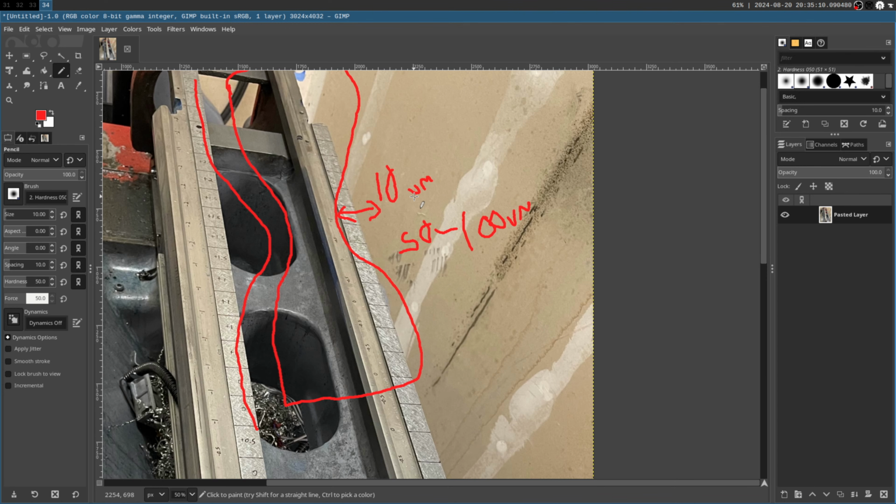The Monarch 10EE that I have, I think its ways were down to 2/10, which is 2/10,000ths of an inch, which is like 5 micron. I think from the factory, that was the original specification. Keep in mind, there's all sorts of components that also need to be square and parallel with each other for that whole system to stack up together, right? And obviously I'm going to be going through that whole system, but I'm starting at the very base, right?